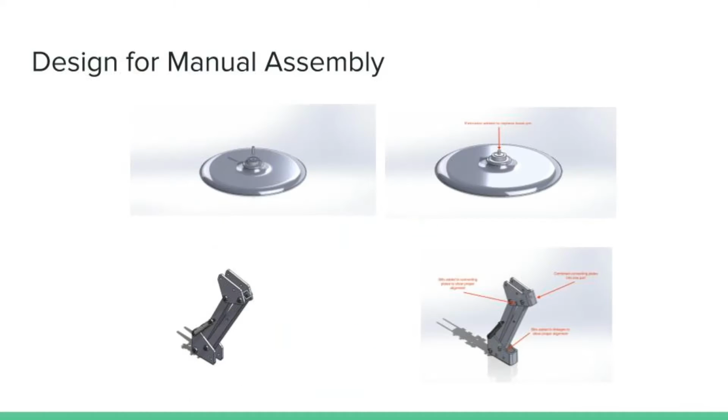this product. For design for manual assembly, we made changes to a platform and module of the original design. The platform we changed was the lamp base. Originally, the lamp base was attached to a linkage arm for both designs with the pin. We modified the base of the lamp to include a small extrusion, removing the need for this pin and following guideline DfAS1, or minimizing part counts.